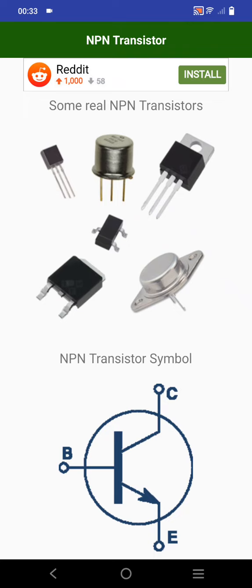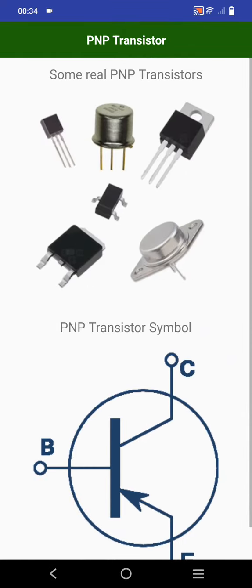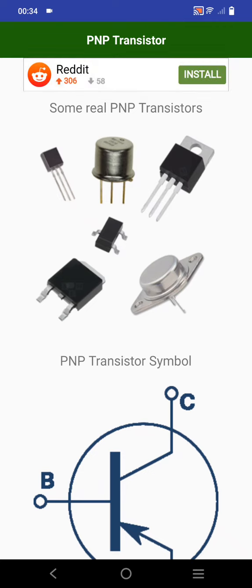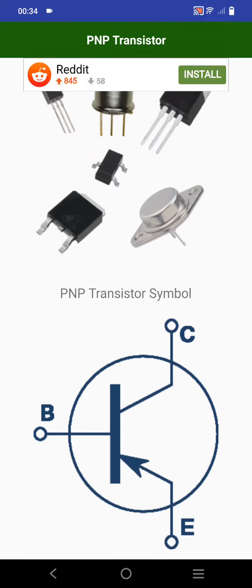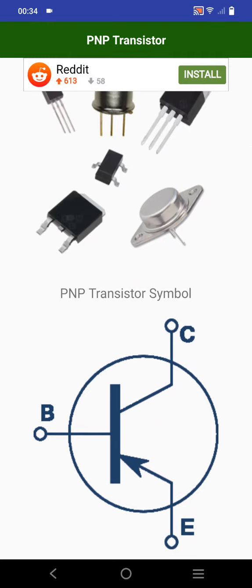This is mostly used in transistors for regulating the current passing through on one side, and depending on the voltage given on the base, it cuts off the particular circuit. That's all. The base is some kind of switch which controls it. So that is for NPN, and then you have PNP transistors, which are somewhat like this. You have positive on this side, so you give positive on C and E, and the base is N, so you have a negative bias.